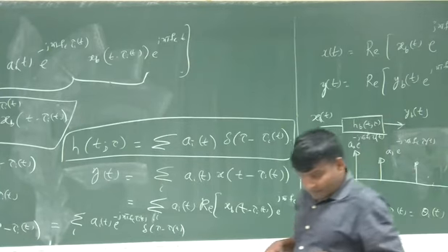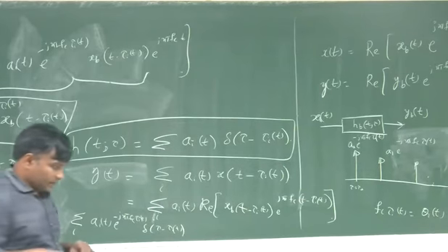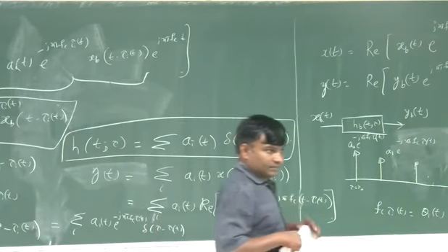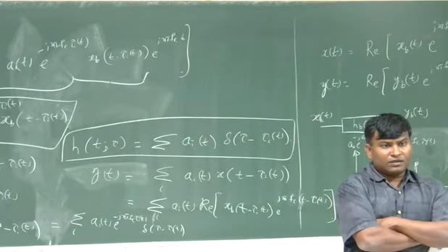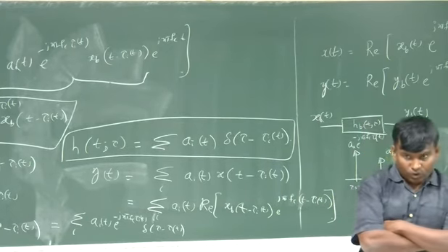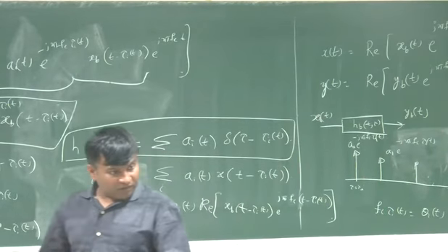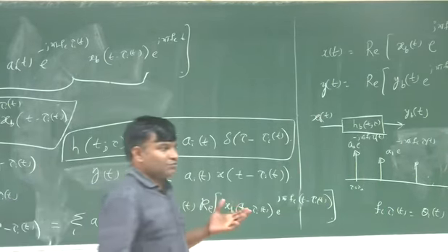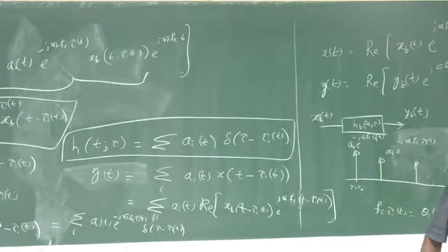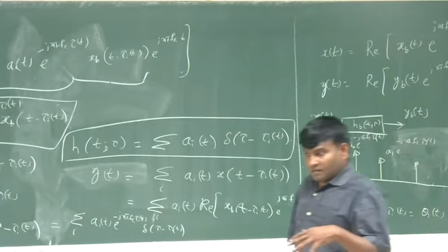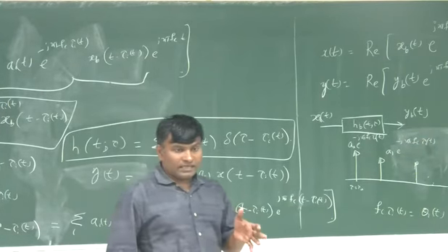And at the receiver, one of the first steps that any receiver does is receive y of t, okay? Then it down converts the signal into low pass form. And then one of the first steps we always do is analog to digital conversion, which is viewed as a low pass filter followed by a sampler.